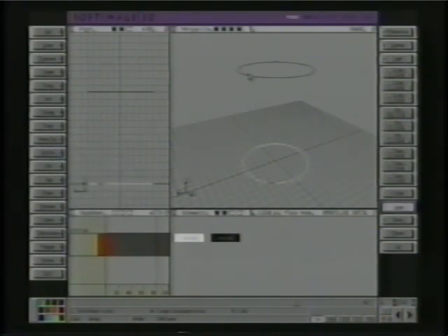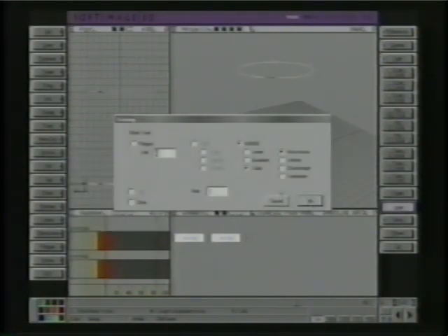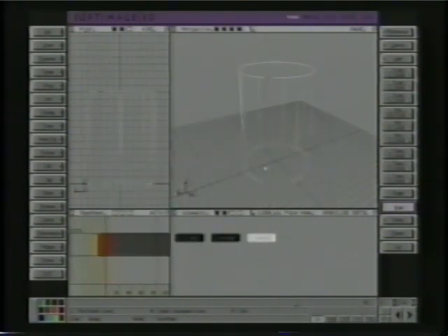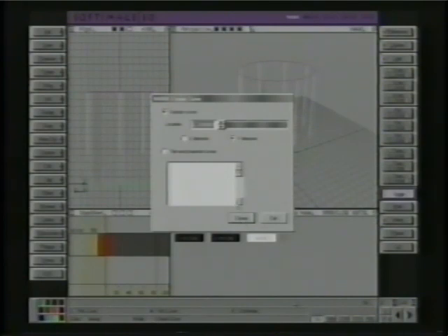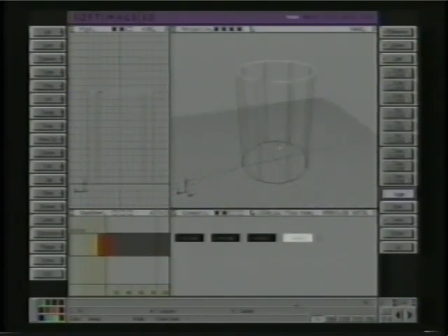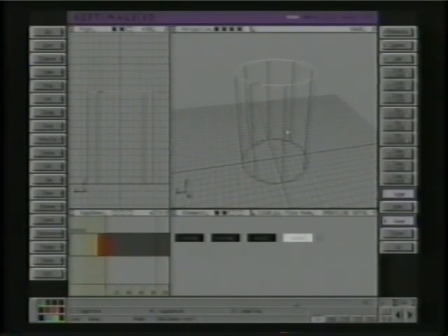Do a surface skin, and going to do a cubic NURBS. And at the top here, instead of making a face, going to extract. We talked about extracting a little bit earlier. Extract one there. Now we have not a face here, but a curve. We go into info select. It's a curve, and I'm going to duplicate this curve.